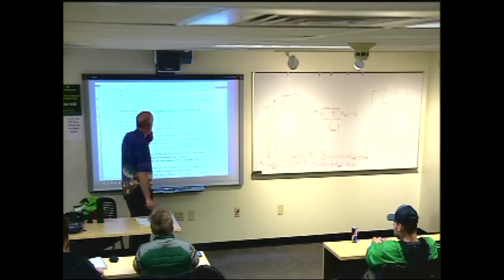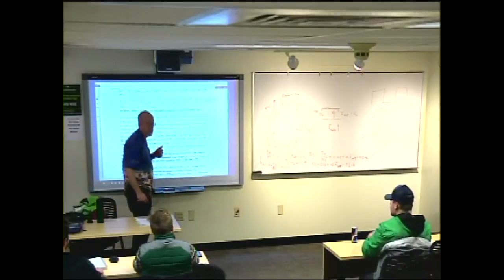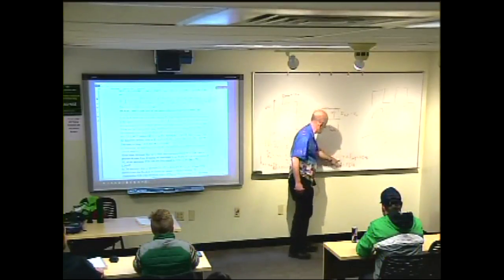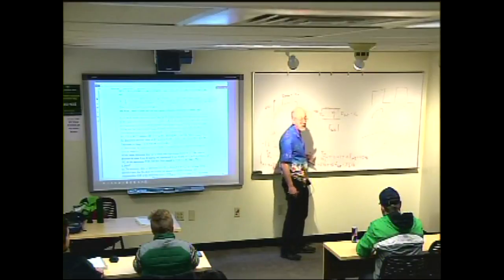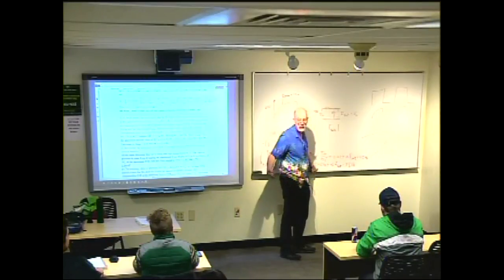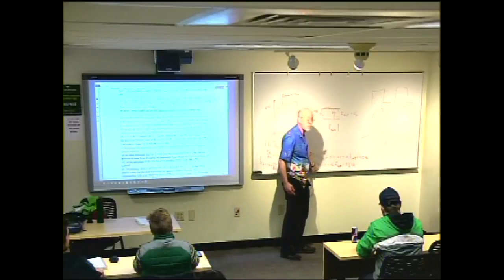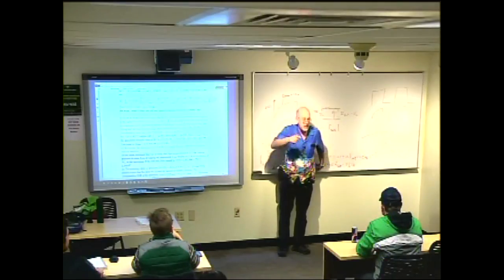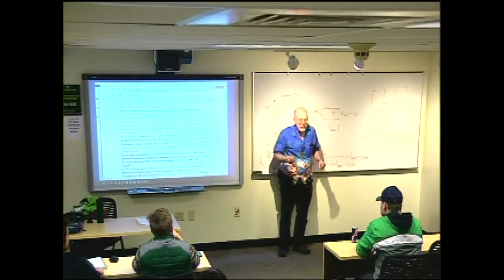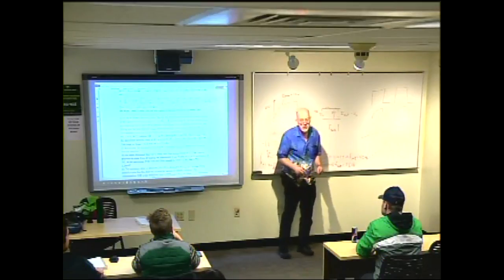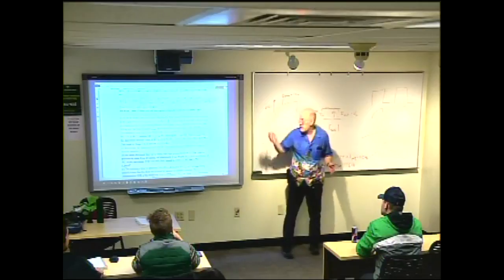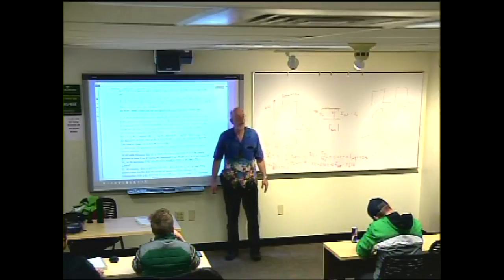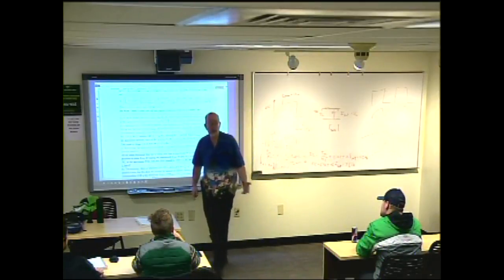Okay. So I would say the maximum value of RC, the biggest that RC can be, is this. It can't be this. Just because this number's bigger than this number doesn't mean that this is the maximum. In fact, it can't be this big, or else it screws up the falling edge. But I understood that the wording was potentially a little confusing, because if you just read and go, okay, I'm going to compare two values of RC and I need the maximum, I'm going to take the bigger one, without thinking through what the impact is. And that's why I got rid of the word maximum when I reworded it, that I apparently didn't share with you. So I apologize, I didn't give you the updated version of it.